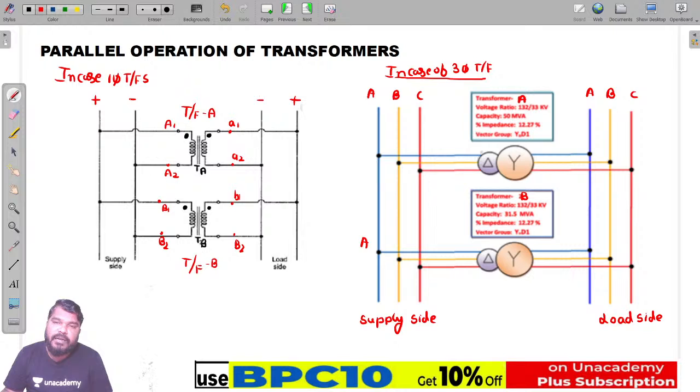The primary winding terminals of the two transformers are connected to the common supply side, and the secondary winding terminals are connected to the common load side. So what we conclude is that whenever the primary winding terminals are connected to the common supply side and the secondary winding terminals are connected to the common load side, the transformers are said to be connected in parallel. Okay, all of it clear now?